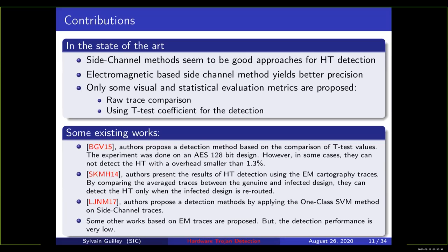We go for a Trojan which is hidden in a RISC-V CPU. So it has nothing particular to disrupt, you see. Imagine, for instance, a Trojan in a RAM. The geometry of the RAM will be changed in a visible way because it is highly structured, whereas a processor is usually synthesized into a sea of gates. So a few more gates from there to there is not going to be that visible.